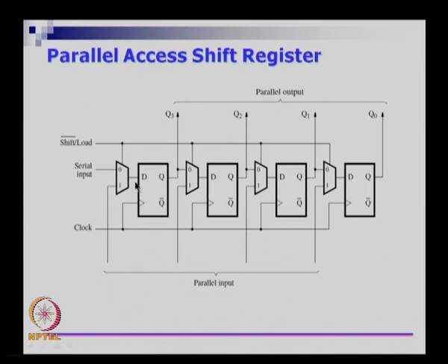So what we have is, we have put a mux in such a way that it either acts as a shift register which is shifting right, or it can do something in parallel. The key thing is a shift register requires n cycles to read the value of a register. If I want to see the contents of these 4 flip flops, and I can operate only in the shifting mode, then I need 4 cycles to see what these bits are. This bit I can see in the first cycle, this bit in the second cycle, this one in the third, and this one in the fourth.